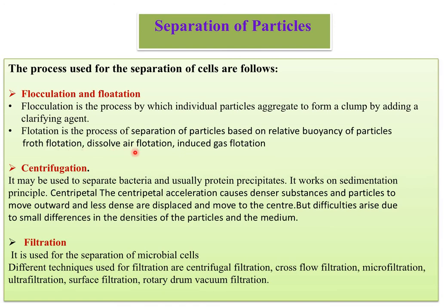Froth flotation, dissolved air flotation, or induced gas flotation. Then moving to centrifugation, it may be used to separate bacteria and usually protein precipitates. Centrifugation works on the sedimentation principle, involving centripetal acceleration, which causes denser substances and particles to move outward, and less dense ones are displaced and move to the center. But difficulty arises due to small differences in the density of the particles and the medium. In that way, there is some difficulty during centrifugation.